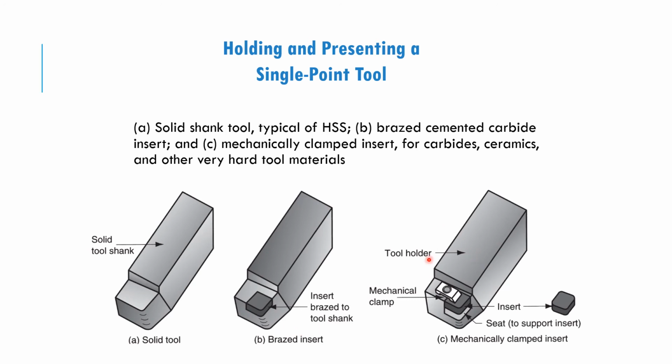Another one is the mechanically clamped insert, which is most commonly used. With this one, you can clamp the insert to the tool holder, and then you can easily open the screw here and replace the insert while performing the machining process.